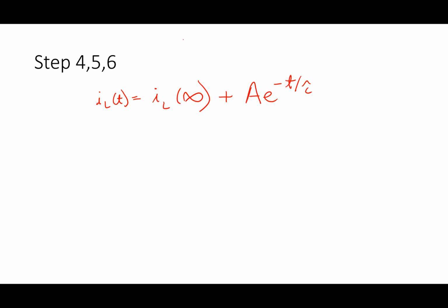All right. And we already said that VOC divided by RTH equals IL of t plus L over RTH times dIL by dt. That was our differential equation. Okay. And we defined tau to be L over RTH. I like working in symbols a lot more than I like working in numbers, because the numbers are different from every problem to the next, but the formula is not. We get a lot more intuition from working with the symbols than with the numbers.